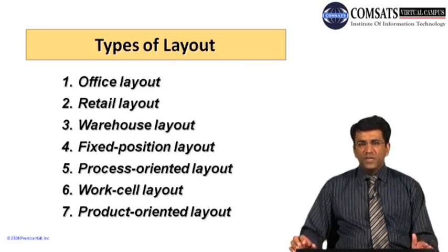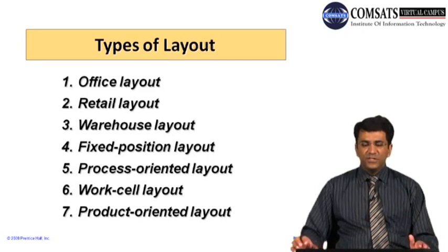So the layout should be such that the maximum inventory can be effectively and efficiently stored, and there may not be handling problems in that type of layout. Then fixed position layout, students. This is a type of layout in which heavy machinery is fixed at a particular location, and the different workers will have to move towards that machinery so that they can work efficiently and effectively.